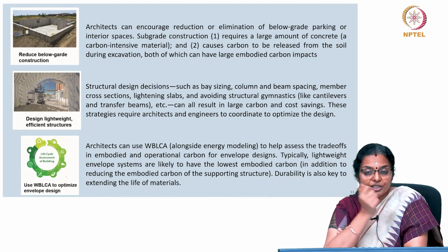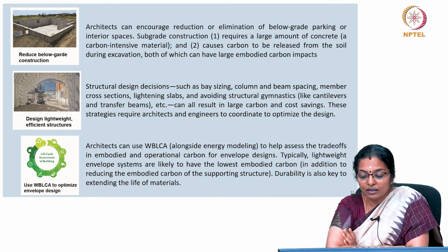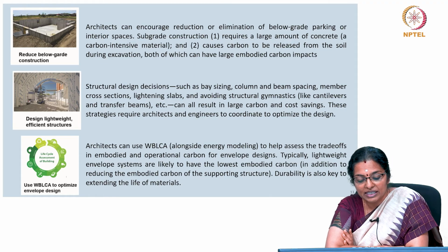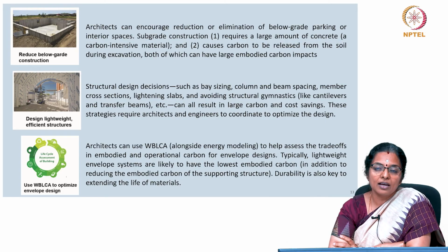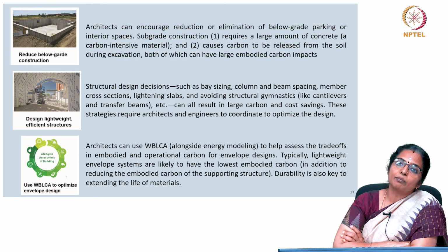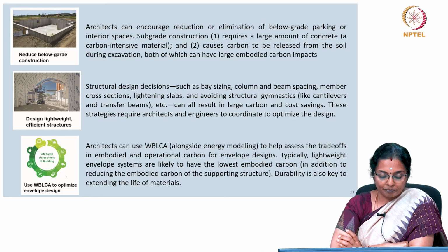Structural design decisions such as base sizing, column and beam spacing, member cross sections, lightening slabs, and avoiding structural gymnastics like cantilevers and transfer beams, etc., can all result in large carbon and cost savings. These strategies require architects and engineers to coordinate to optimize the design, along with an awareness by the client.